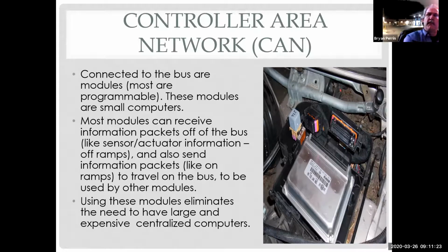For example, going down the road, my engine control module is pretty busy, but my driver's door module probably doesn't have a lot to do. So it has the capability of performing certain computing tasks if other modules need extra computing power. They're able to put that out on the network and basically get other modules to do some of those computing functions. So we don't need one large central processor or one large central computer. We're able to use the entirety of the network to do more complex problems and put that stuff back. So it's really interesting how the networks are built.